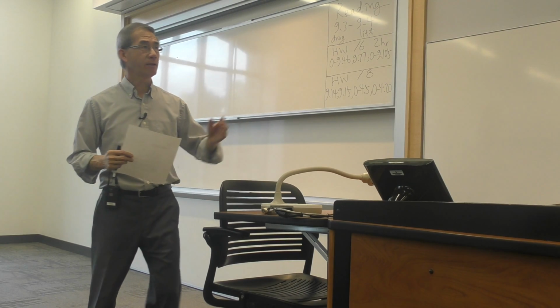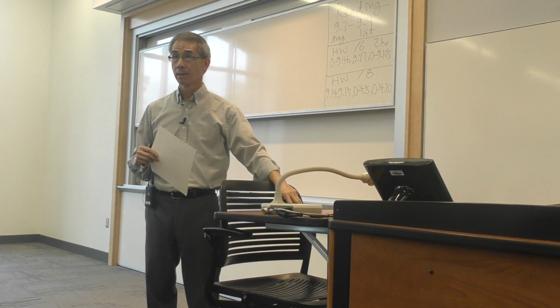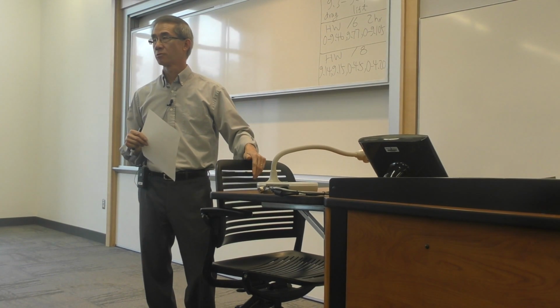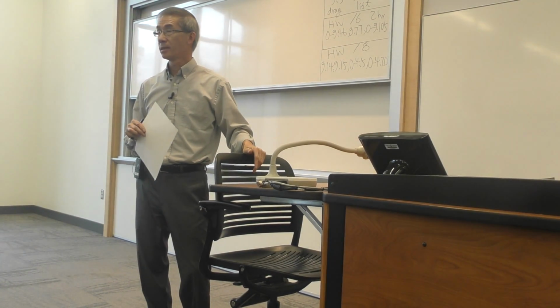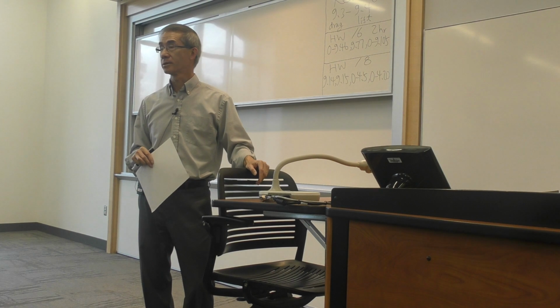Yes? For what Reynolds number do we consider there to be a boundary layer? Anything that is more than a couple of thousand. Again, it's a gray area, but when you are at 500,000 Reynolds number, for sure you can assume the concept of boundary layer can be used. All right? But a couple of thousand is very, very marginal. If you want to be safe, don't use the concept of boundary layer.